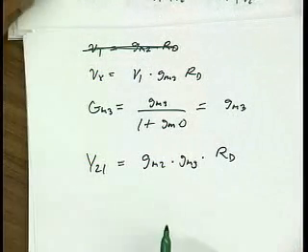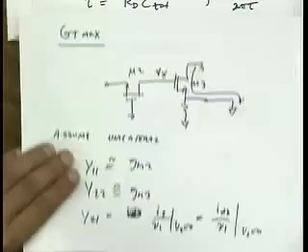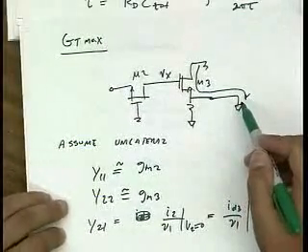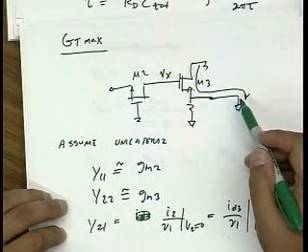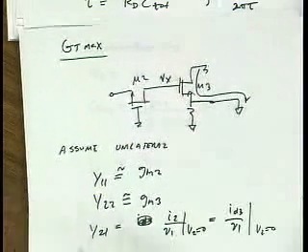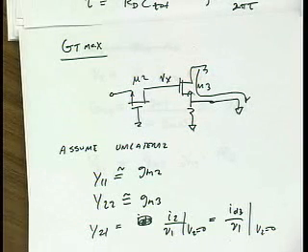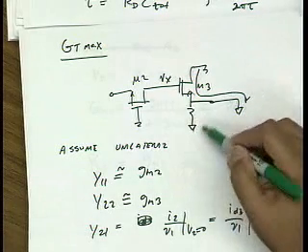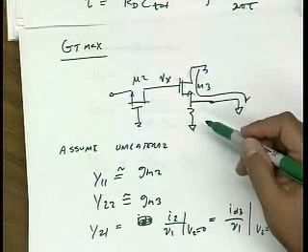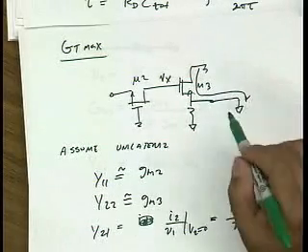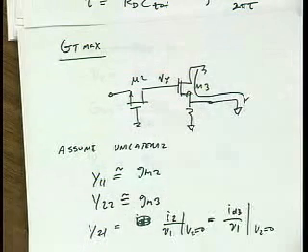Okay. Yes? Because we short the output to calculate Y21. Okay, can you repeat your question? All the Y components, Y11, Y22, don't take into account... I mean, it doesn't matter whether you consider the amplifier or not because you don't involve the R feedback at all. No, it does matter. Let me explain. Let's say we're calculating Z parameters. If we're calculating Z parameters, this degeneration would matter, right? It's just when we calculate Y parameters, we short the output, and it makes the calculation much simpler. But I don't think I got your question, actually.